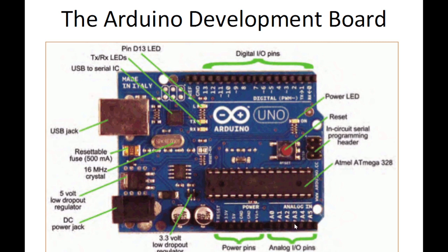So these are all input analog channels. By applying voltages within the range at these inputs and programming appropriately in your Arduino program, you'll be able to read the equivalent digital values for the respective analog input channel.